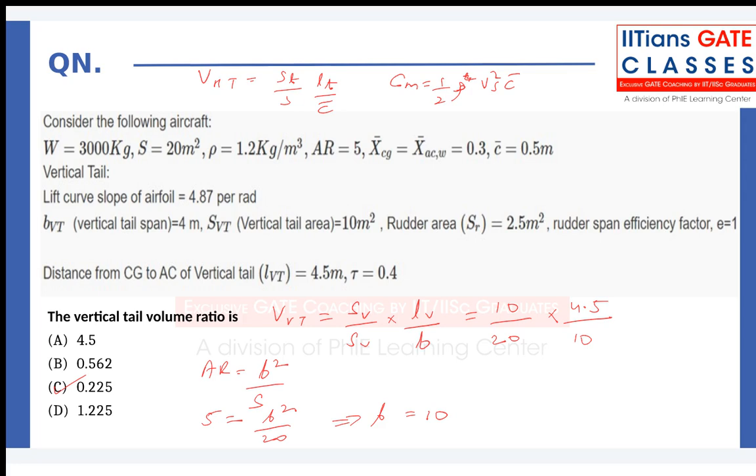In that case, your Cn would have a B in the equation. So it will all be divided by B, and in the horizontal and vertical tail volume ratio, you will have B. This basically happened because your vertical tail is along the negative z, in the perpendicular axis to your horizontal tail, right? So the wetted surface area changes, so the reference area changes.